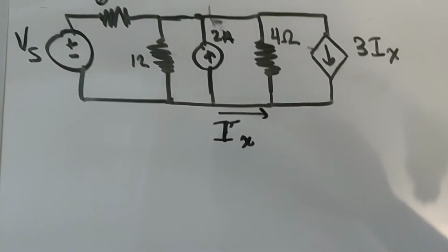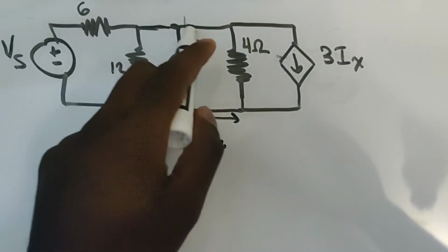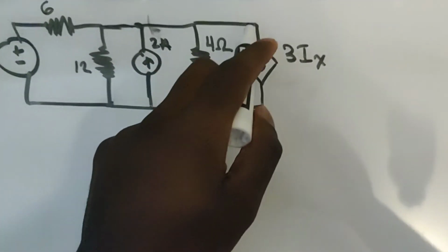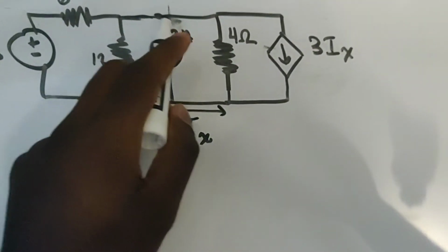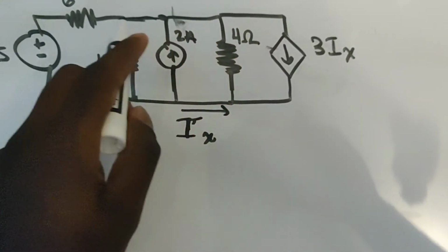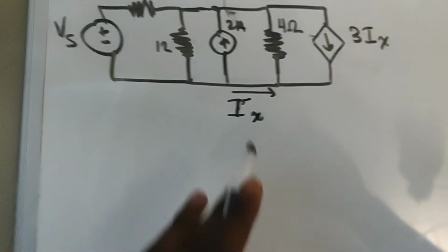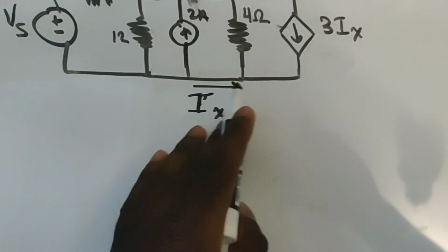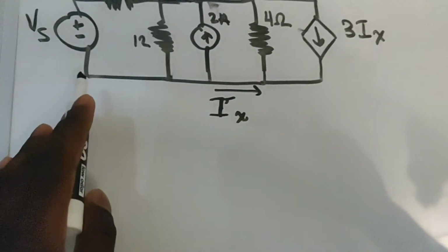And so notice how we have no components between these wires. So this whole wire is acting as one node. So you can go ahead and split that up or join however you want to solve the problem. And also, if you notice this bottom piece right here, there's nothing connected between these nodes.